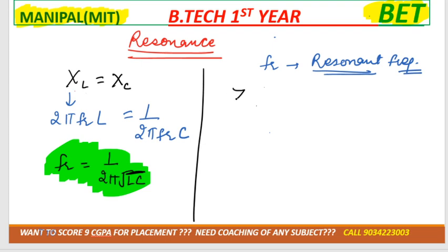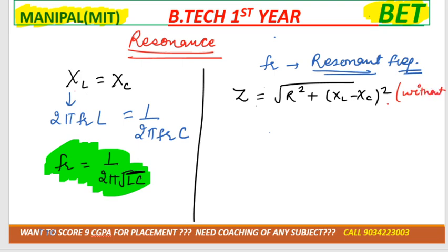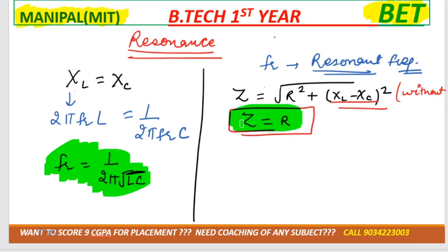If XL is equal to XC, then generally what is the formula for Z? That is root of R square plus (XL minus XC) whole square, right? That is without resonance. But with resonance, XL is equal to XC, so Z will become equal to R. So this is another condition of resonance, that Z is equal to R. In the case of resonance, will impedance be minimum or maximum? Impedance is reducing, yeah. So impedance will be minimum.